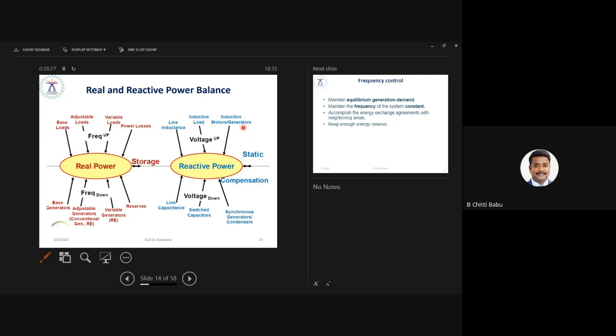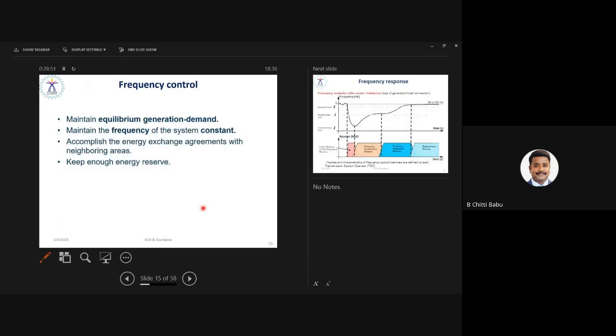They require reactive power from the grid, so they draw more reactive power, eventually affecting the voltage. This is what we need sometimes: reactive power compensation, because solar photovoltaic or wind energy conversion system generators do not support any reactive power, right? That is why we use energy storage devices for the support of both active as well as reactive power in today's power system, right?